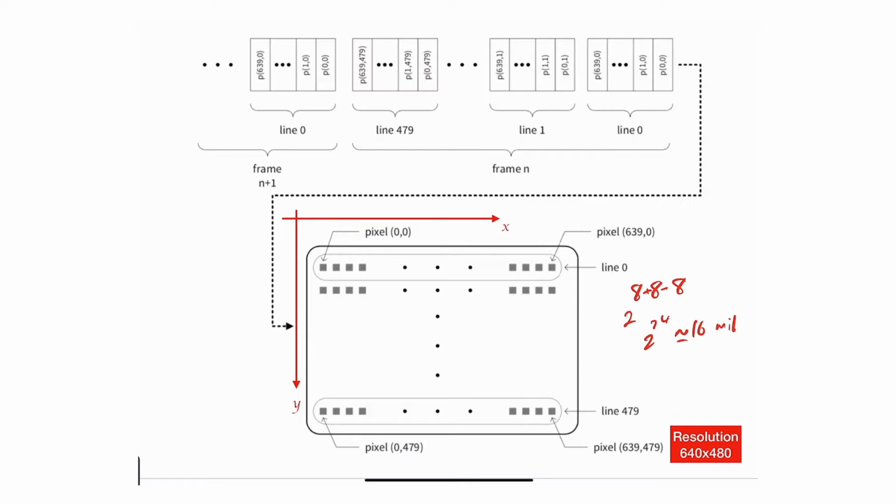However, this will require a lot of memory, and since we are dealing with embedded systems and we're building this on an FPGA, and we will build that particular controller on the Nexys 4, we are going to restrict ourselves to 4 bits for each one of the colors, so half a byte basically. So we're going to have 2 to the power 4 plus 4 plus 4, and that will give me about 4,096 colors. That's actually more than enough for our purposes.